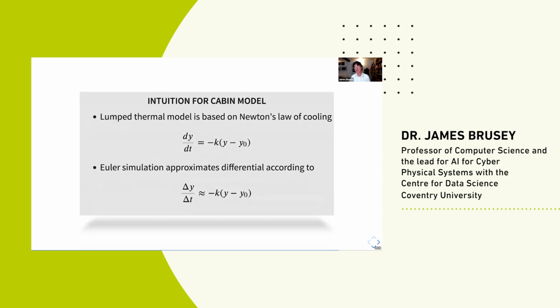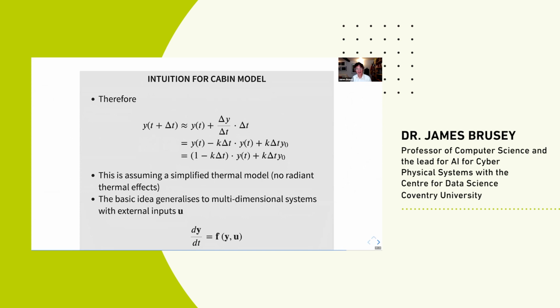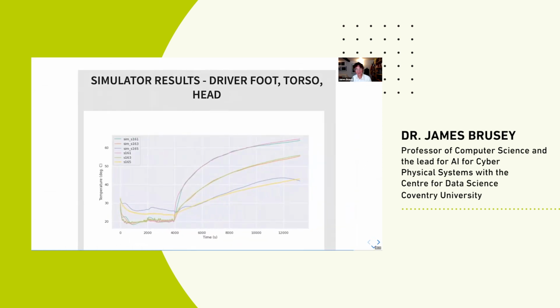And actually, the more I look at it, the more I find that a lot of people are converging on this approach. The nice part about this particular problem is that it's linear in terms of its differential equation, if you can ignore radiant heat. And so therefore, that means that you can model the differential equation with a linear model.